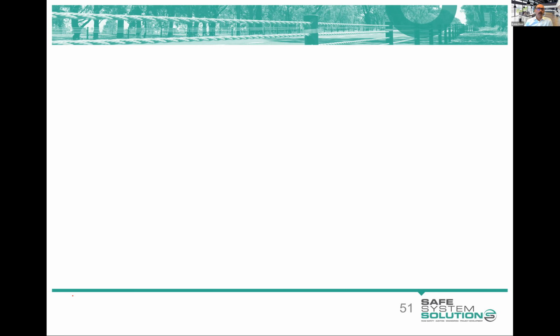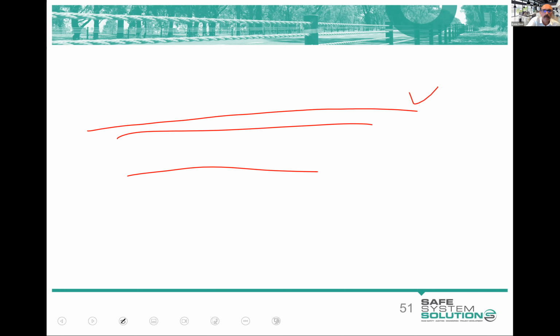So the question is, is it all then only about lowering speeds? Well, it's not. Speeds at intersections usually have to get lowered, but here's a few examples of high speed primary treatments. You've got a roadside and a continuous barrier system. That is a primary treatment. People can go fast, they leave the road, they hit the barrier, they run along the barrier. It virtually eliminates death and serious injury from run-off-road for passenger vehicles.